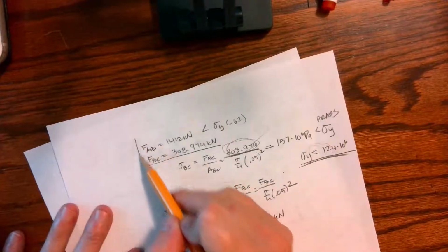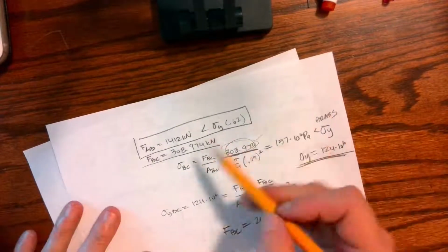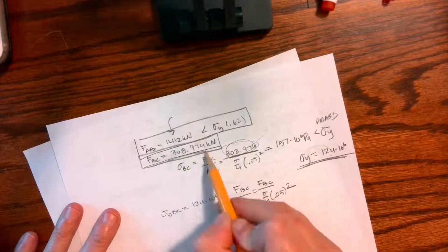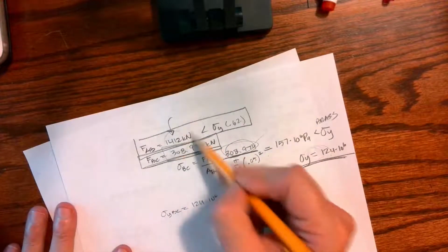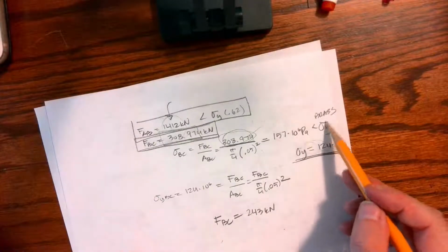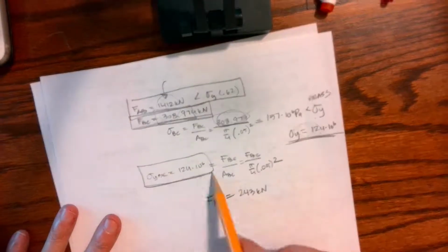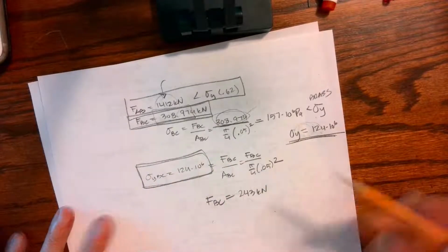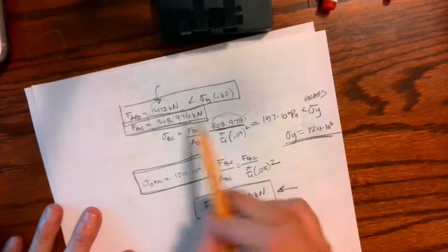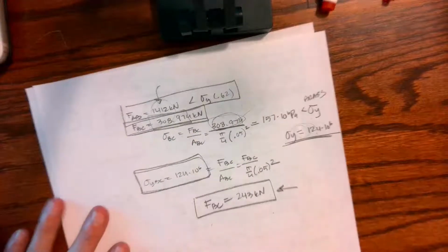Okay, so I designed and I based it on the yielding of material AB, and I calculated an internal force of 1412. That put my force in BC at 308. So I can see that that P was about 1700. But when I checked yielding, the brass yielded. So I have to go back now and use that brass value. My yield stress of the brass is limiting what that force can be. So the most that we can have in the brass is 243 kilonewtons, not the 308 we got when we used the aluminum as the limiting.